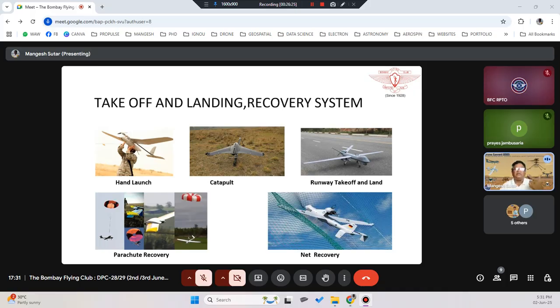That's why it is not so successful to have the parachute mechanism in quadcopters, what we call rotorcrafts. In fixed wing aeroplanes, normally we can have it because they fly at very high altitude, 10,000 feet, 20,000 feet. So there we can utilize a parachute for the recovery system.